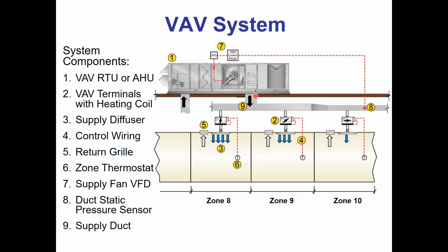The air handling system's job in life is to provide me 55-degree cold air all day long, no matter what. He doesn't do heat. He's just a 55-degree cold air machine. He provides that cold air down into this duct, and then each individual zone has a thermostat controlling its damper to decide if it wants more or less of that cold 55-degree air. So if a zone is hot, it'll open up its damper more and more and more, like we have on this first zone. If a zone starts getting cooler, it'll start shutting its damper off.